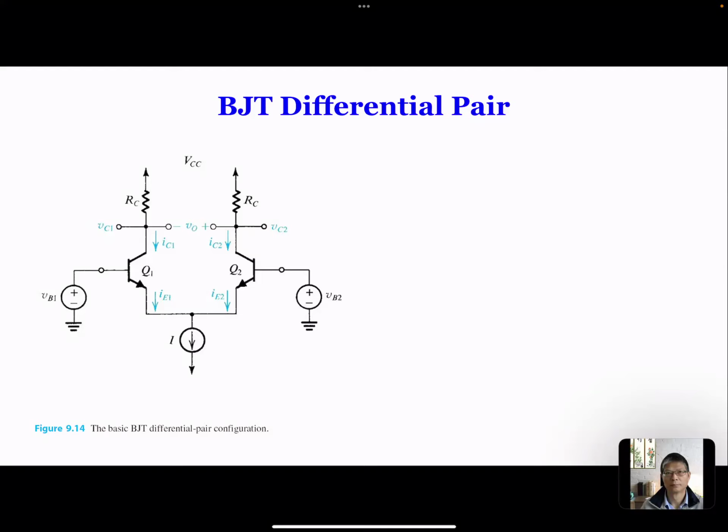But you might ask, how can you get the 0.7? Well, because this arrow means the bottom is a voltage source, so this is a negative something, 5, 10, 15 volts negative, and this is some voltage drop. If this is an AC signal, for DC this is a short circuit, so this is ground, and this will be minus 0.7 volts. That's for DC, minus 0.7.